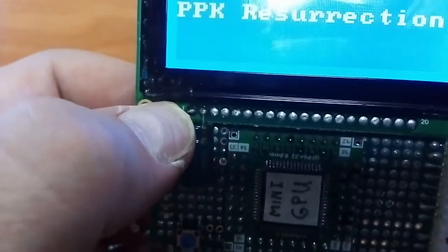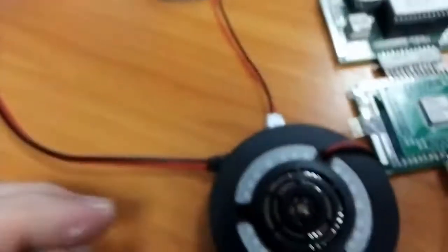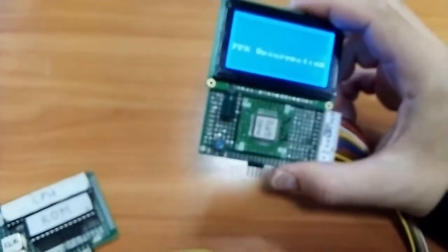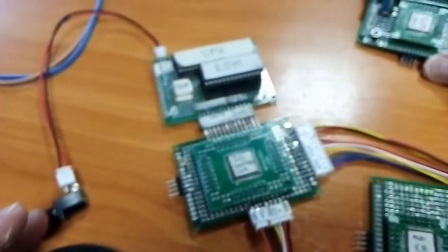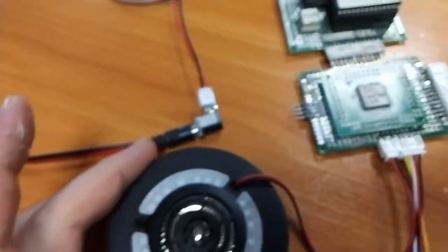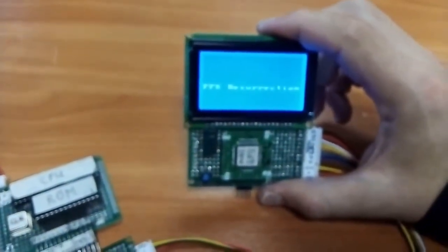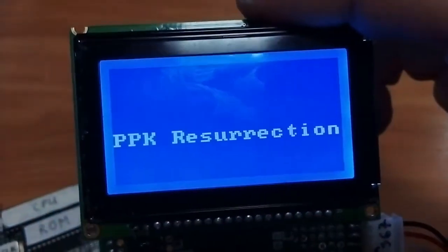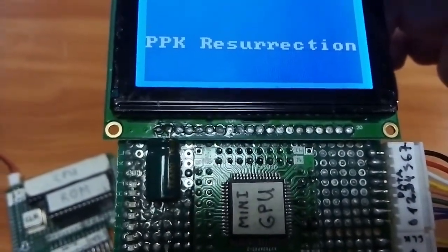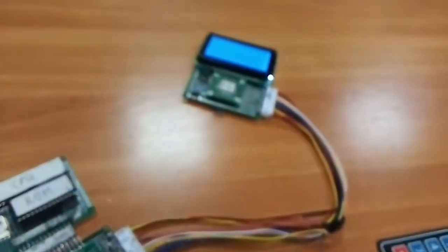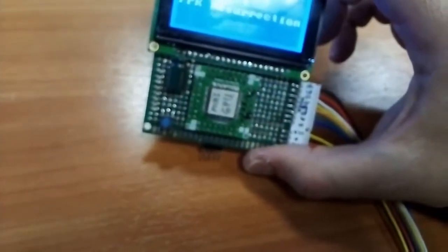I put a capacitor here between plus and ground at the power. That's because if I don't use a capacitor, then the sound that goes out from here is dirty, just because this screen makes the current dirty. This screen is somehow cheaply made, and it spoils the current. So we have a capacitor, the module of capacitors I've put there. That's 2000 microfarads. Do you remember microfarads?